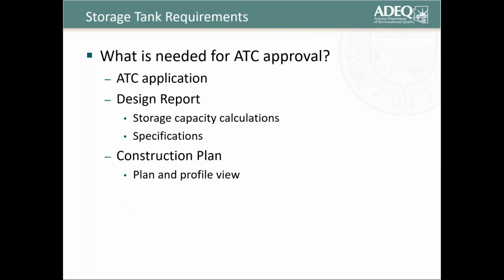And now let's look over the storage tank requirements for an ATC approval. Again, that ATC application completely filled out. And then for the design report, we do look for the storage capacity calculations, making sure that the amount of storage is appropriate for that water system, whether it's a small, medium, or large water system. And then the specifications for that storage tank. And then in the construction plan, we look again for that plan and profile view to make sure that all the required components are associated with that storage tank.